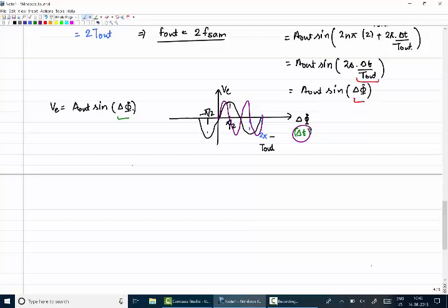So in terms of the phase error delta t, what happens to the gain of the PD if my output frequency changes? It does not remain the same. It varies, right? And if we analyze this in terms of time error in the PLL, you will find that the gain of the phase error detector varies with respect to the output frequency.